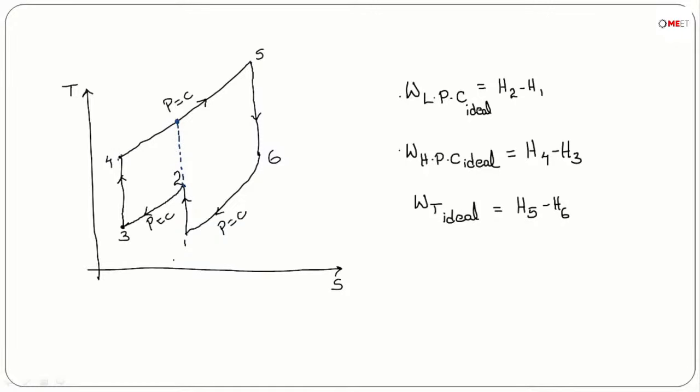As a result of more heat addition, the thermal efficiency will not increase compared to that of the Brayton cycle. So in this particular condition, intercooling, we were able to improve the pressure ratio to a greater extent, but we were not able to improve the thermal efficiency even though the gross work output is increasing.